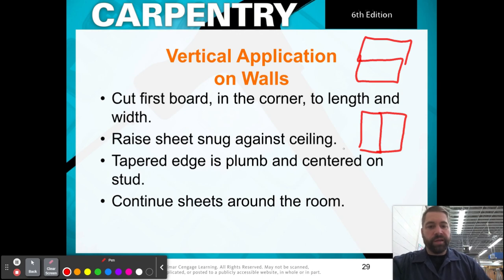Raise the sheet snugly against the ceiling and make sure that the tapered edge is plumb and centered on the stud. This is important because when you start in the corner, that's going to set the tone for the rest of them. So if you make a mistake here, it's just going to carry through and possibly get worse. So always make sure to correct as you go.